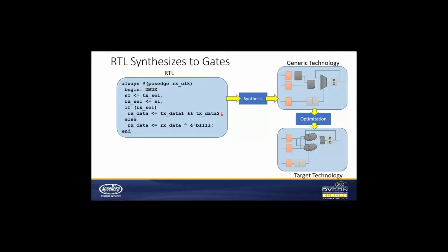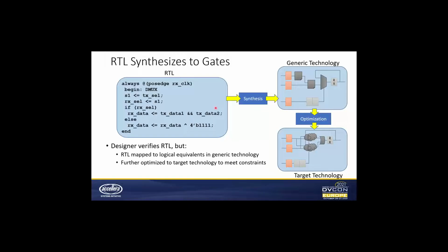Similarly, due to scan logic insertion, a clock tree can be impacted because we may have missed the constraints to provide for the proper modes of the design, in which modes we run the design. So the question can be raised: if the RTL is correct, and we are mapping my RTL logic to some logical equivalent in the generic technology or some specific technology, depending on the constraints that are there, maybe area constraint, timing, such optimizations, does my synthesis introduce new issues or not?